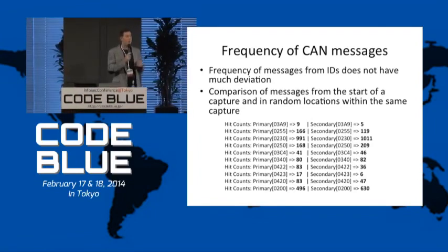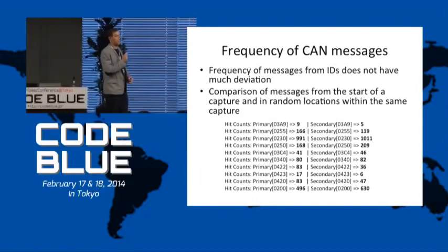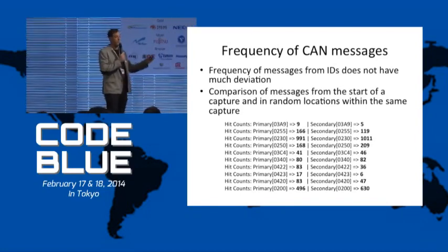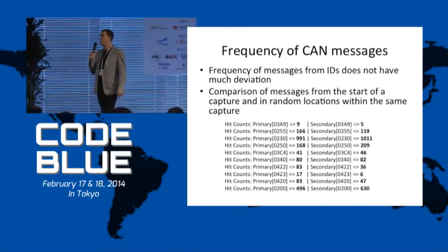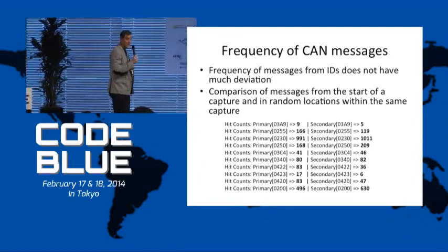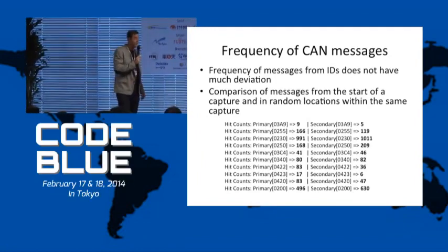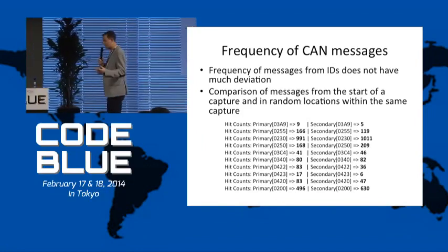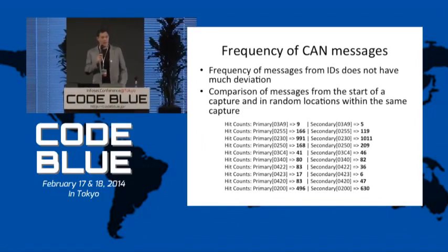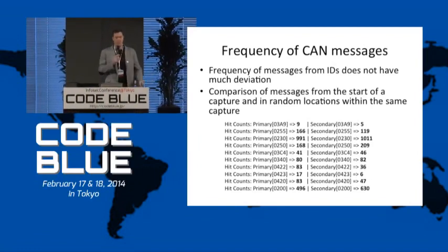As I said before, how we got steering to work, we flooded the network with invalid speed messages. This, again, would stick out. If you're used to seeing 100 speed messages a millisecond and you're seeing 10,000, at the very least it's suspicious, and at the most it's malicious. These are easy to detect because cars are pretty standard. As a manufacturer, you know what you should see on your networks.